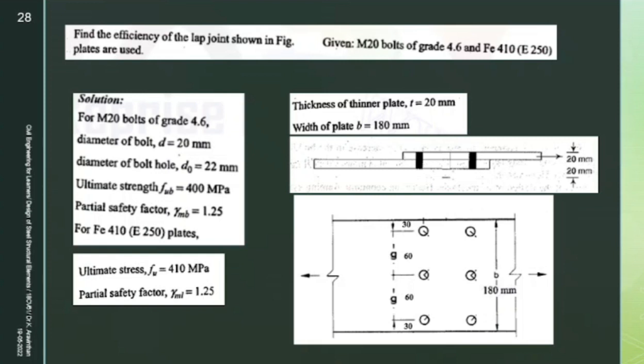What is efficiency of the joint? The plate will be having different capacity and the bolt will be having capacity, that is strength, bearing capacity. You have to relate that and find. In hydraulics you would have found the same efficiency. What do you mean by efficiency in hydraulics? If your turbine is having 33% efficiency and a Kaplan turbine might have 52% efficiency, which turbine you will be using for your power generation? 33 or 52? 52.